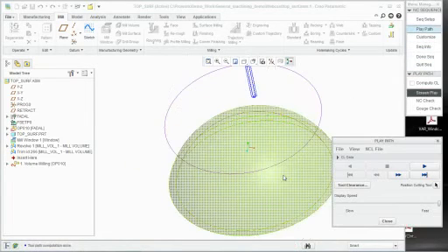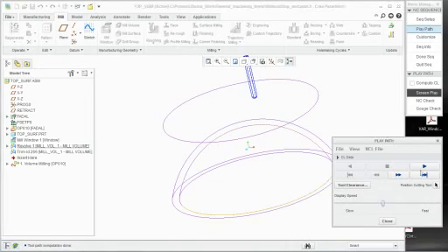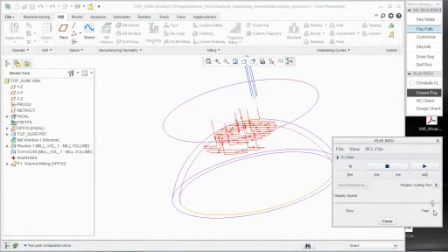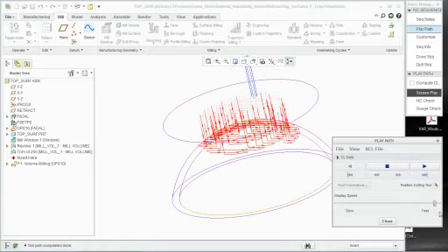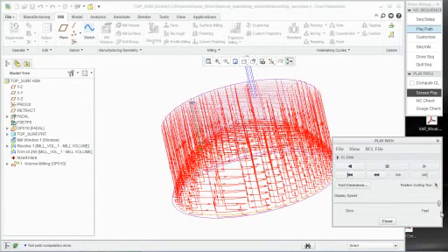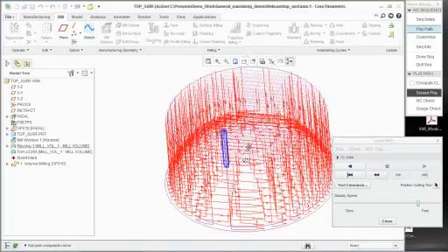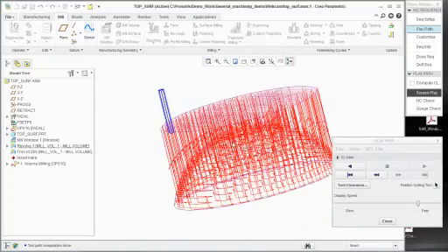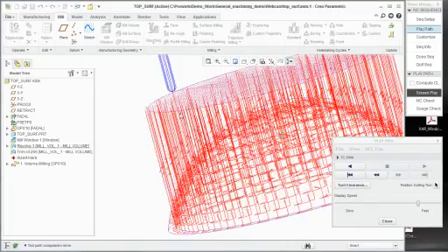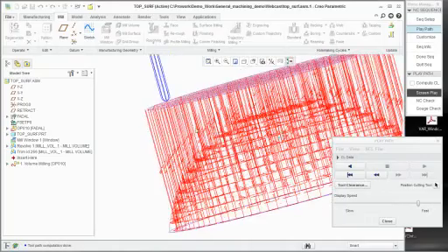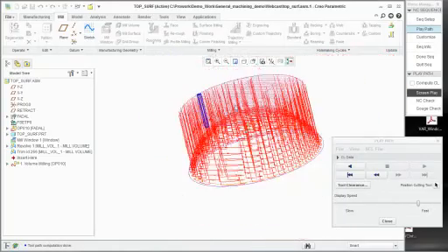And now what you see here, slow this down, is that notice how it pays attention and conforms the shape to the top, and you have some pickups right there, but it actually conformed the shape, and you don't have all of that milling that started off all the way at the top. If I changed the way that it was machining, you wouldn't get all these retracts.